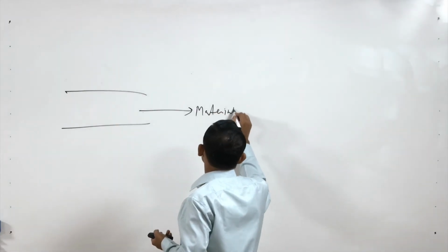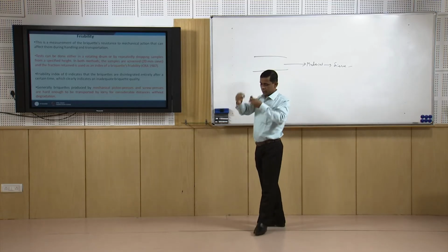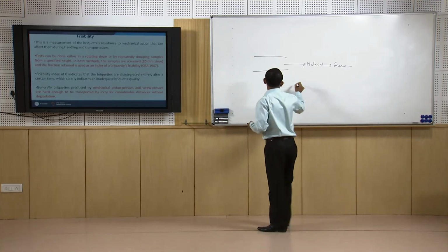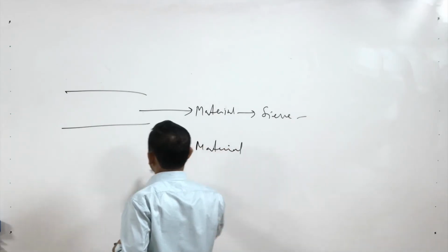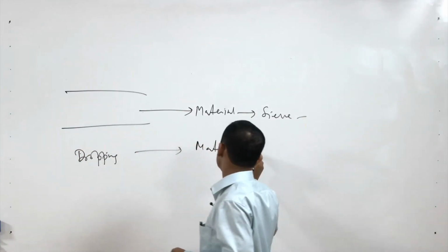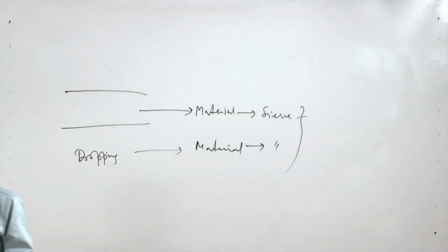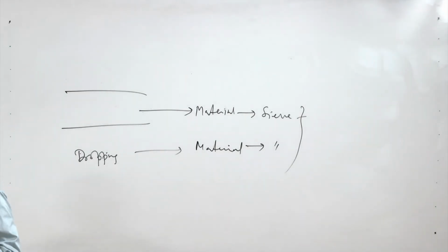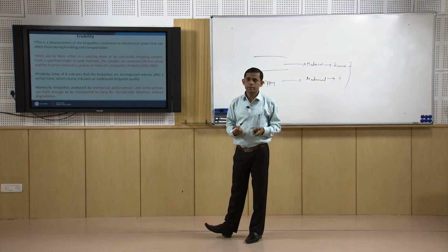and we sieve it, or we can drop it from a certain height several times, then collect the material, and that is also sieved. So, any process we can use, we have to get the final material and we have to sieve it. After sieving we use a 20 millimeter sieve. How much material is retained is used as the index of briquette's friability.